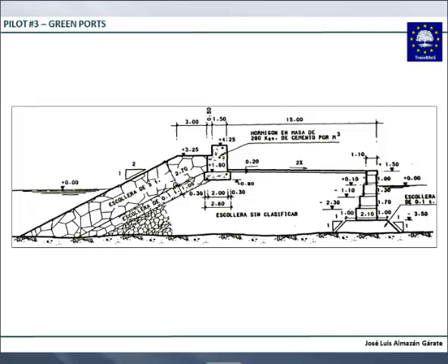So you use this part of the dike to fight against the energy, and you use this part of the dike to support the main structure, to have quiet water, and then you take advantage of this part of the dike to use it as a quay. They are in the same thing, but this side has nothing to do with that side, although they are both parts of the same system.